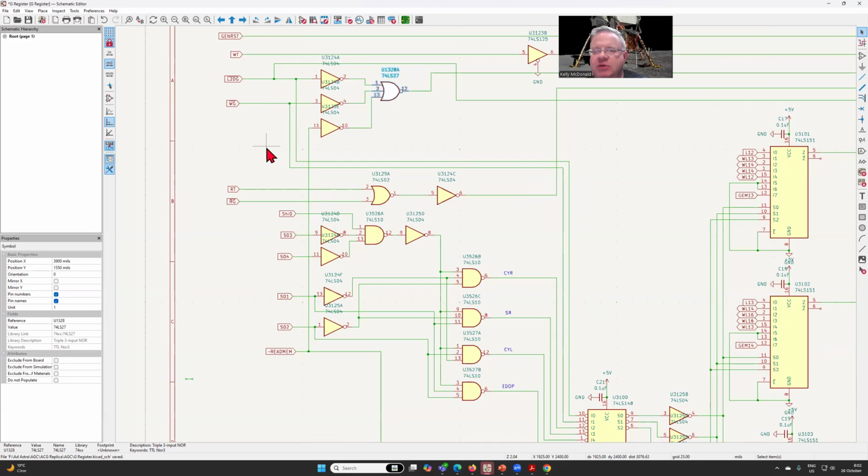And so you may wonder, what about all these editing controls? These editing controls are actually triggered on a WG command. So if I do WG and the S register is set to any of those combinations, like 020, 021, 022, or 023, it'll do these shift operations. If it's a different address, it'll just straight write the contents of the write lines into the G buffer. So that will solve our problem here.